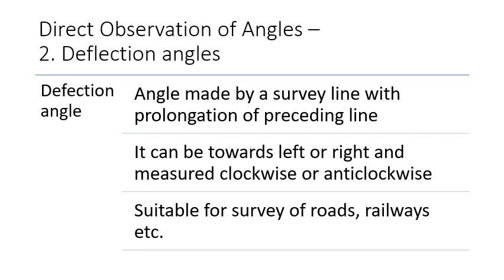Now let us move to the next method. Again, observing the angle. Here we are going to observe the deflection angle. So what is deflection angle? It is the angle made by a survey line with the prolongation of the preceding line.